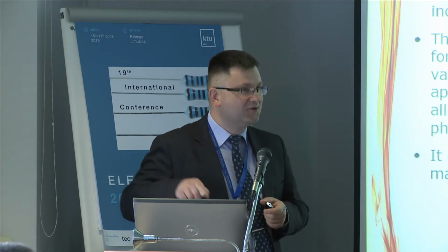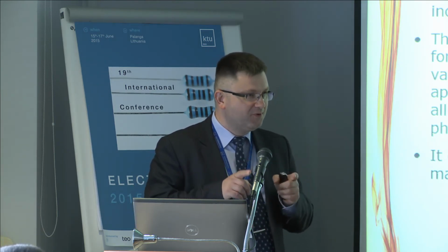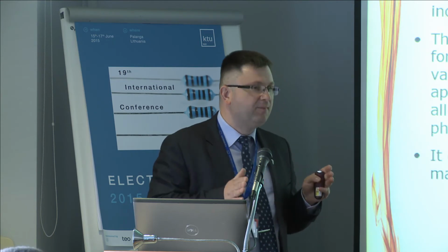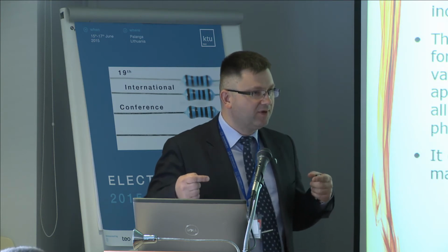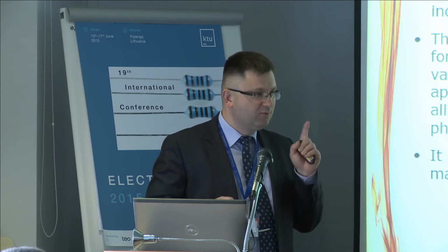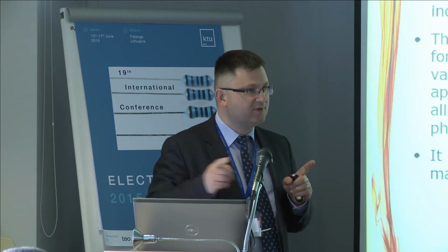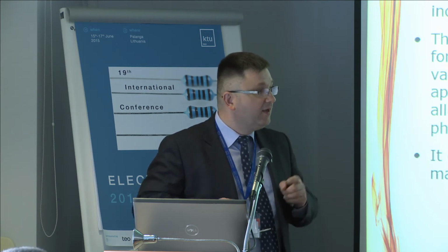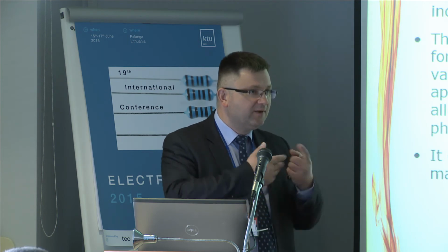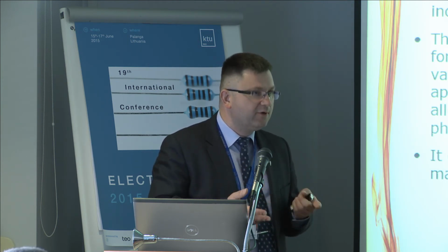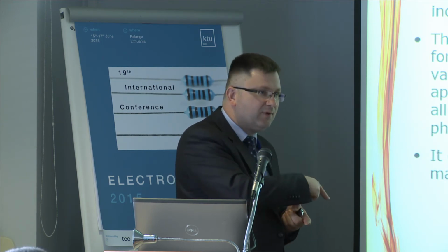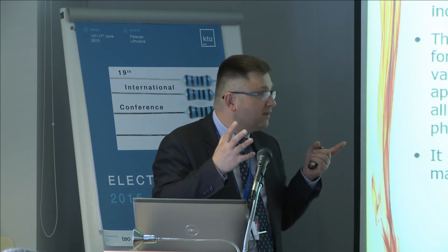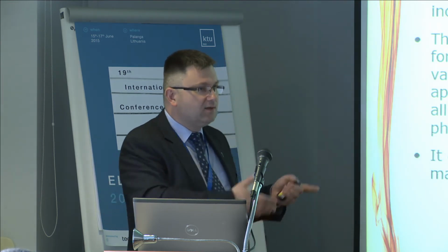We have started to apply such a sensor in order to measure temperature and strain. We have applied such a kind of sensor to our circuit, which is based on double current supply. First was a strain gauge, and the other one was a temperature sensor, a PT100. And in our experiments during deflection, we had a lot of errors in measuring the proper value of temperature. That is why we have started this examination. What exactly happened, we can see in this picture.